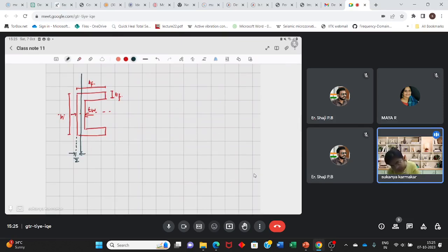Then we can write, for calculating the equal area axis, let's first write the area which is on this side. How much is this area? This area is h into z bar, and equated to the area on the right hand side, which is h times the remaining (tw − z bar). This is one term, and the two flanges which are left, which is (bf − tf) into tf times 2.